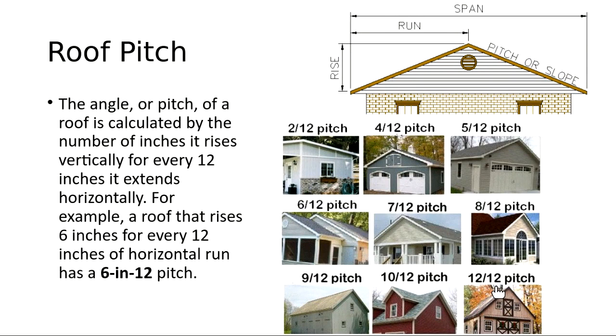So when someone talks about roof pitch, that's all they're talking about. It's the rise over the run. The run is always defined as a 12, and the rise is how many inches it goes up for every 12 inches it goes over.